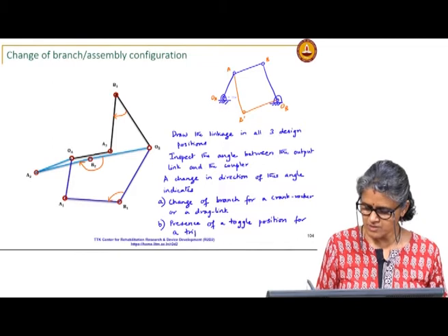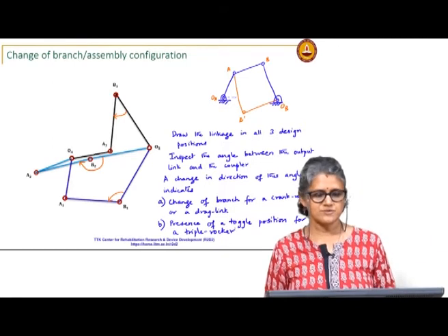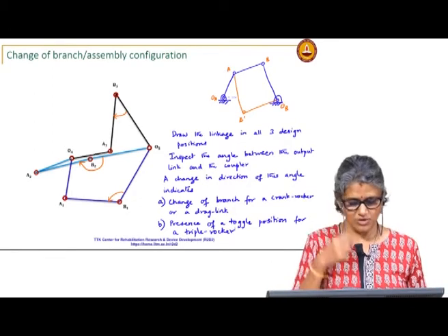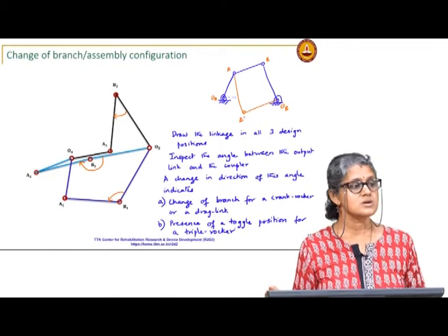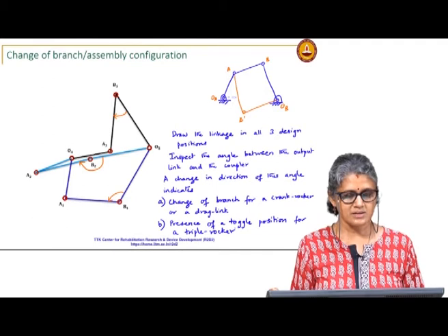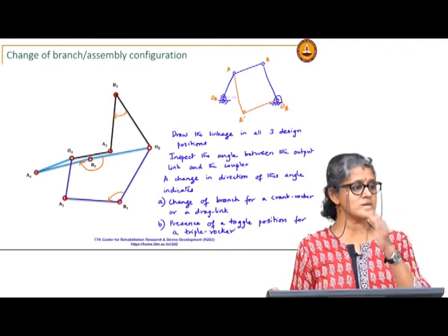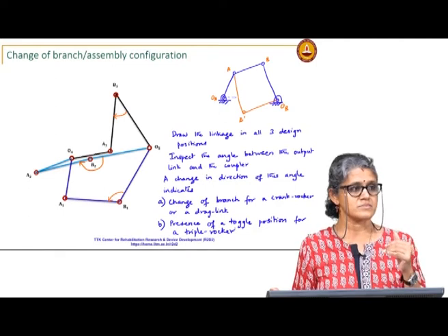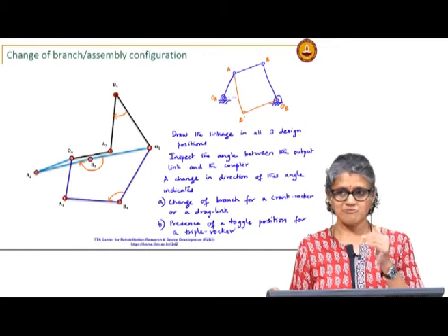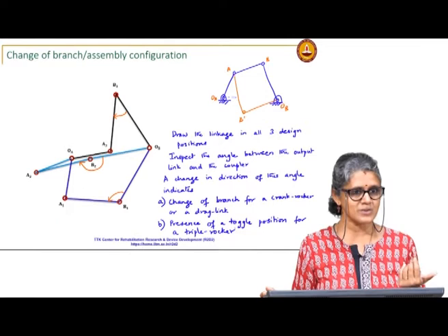For a triple rocker, which is non-Grashof, this is a quick way you can determine whether your solution is going to perform as indicated. Again, the other problem could be how it reaches the positions 1, 2 and 3. We have not said anything about taking that into consideration while doing the graphical analysis.